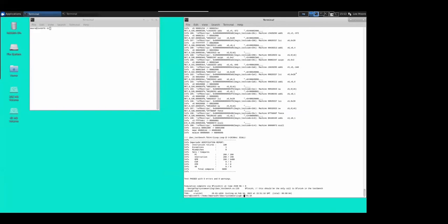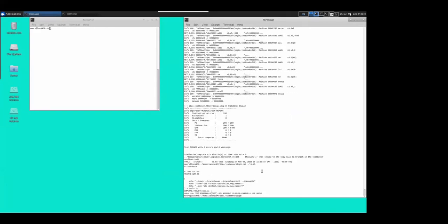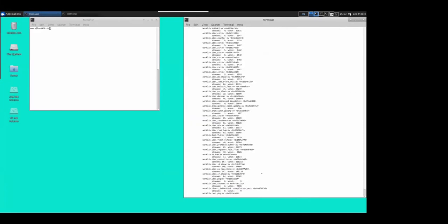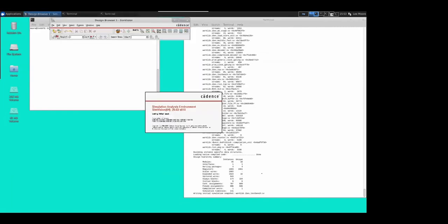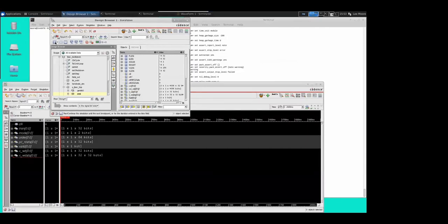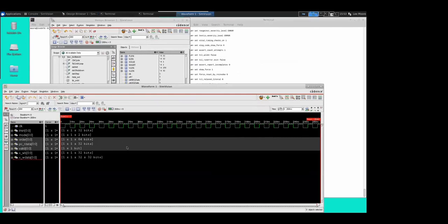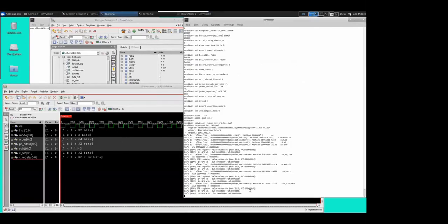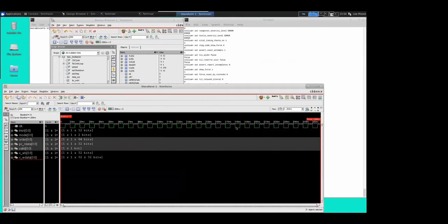SystemVerilog domain. So again, I've got a script set up here. What this is going to do is run up a Verilog waveform viewer, and we can take a look at the content of the RVVI interface that is being driven from our RTL model. I've already pre-selected some of the signals here to make this a bit quicker as far as demonstration is concerned. But the important thing to note is I've gone back to the point where we've got the bug inserted in the RTL, and so we see after 5 miscompares that we're going to perform a finish of the simulation at this point.